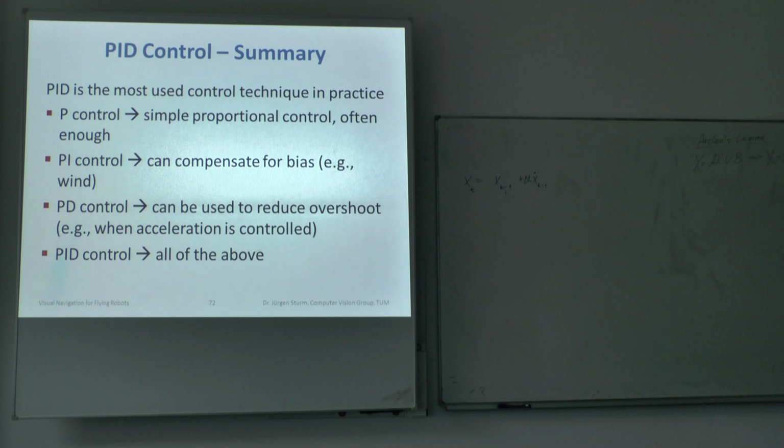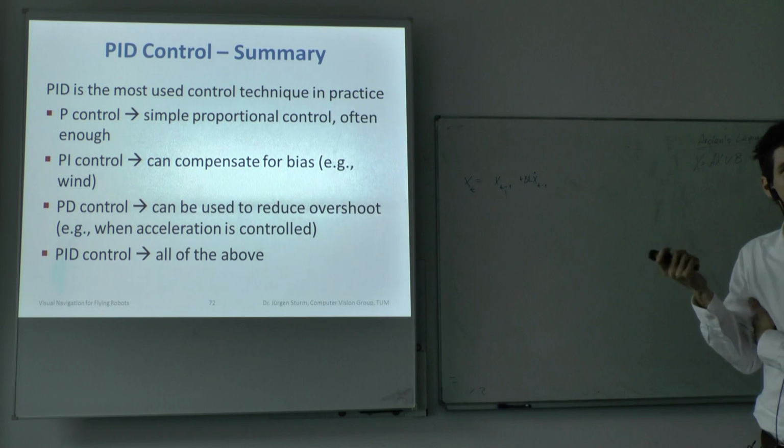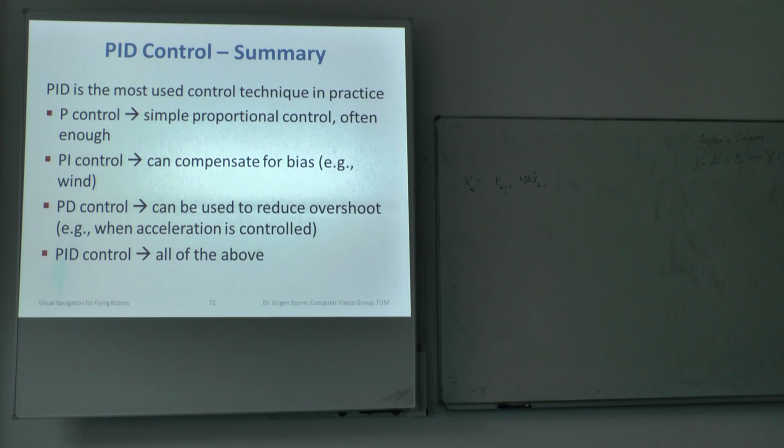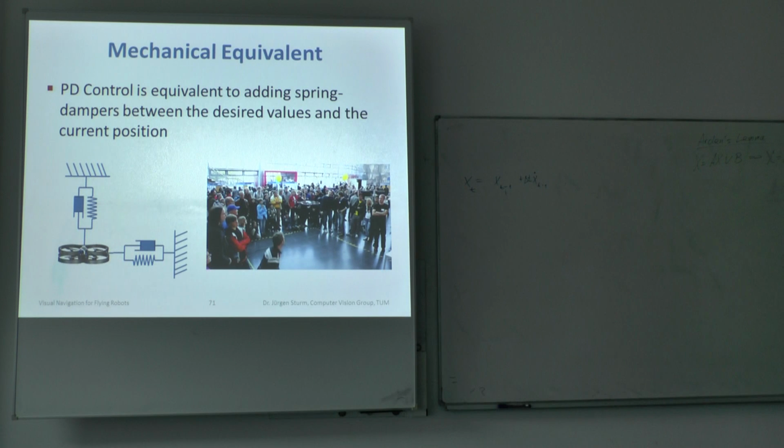It can be any combination, actually. P stands for proportional, D stands for derivative, and I stands for integral. And PID is usually the term that people use to refer to this kind of architecture, because if you don't want the integral part, you just set the coefficient of the integral part to 0, and then you get a PD controller. But you have all combinations, and depending on your application, you just need P control, for example. Can you get a picture of how it's related with the spring PD control? Yeah, right. So in this case, it's just PD control. You don't have an integral part here.